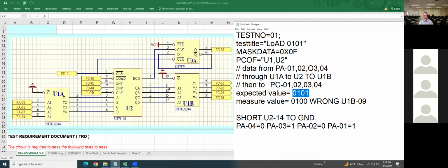U1 is defective? In 14, U2. No, forget that 14 for now. I say something is wrong on pin 9. Okay. Then you go back to pin 11. Basically, Mr. Pham, you're saying on U1B you have the right input at 11, but the wrong output at pin 9. You have to fix the problem. You have to tell exactly. Well, you would replace U1?